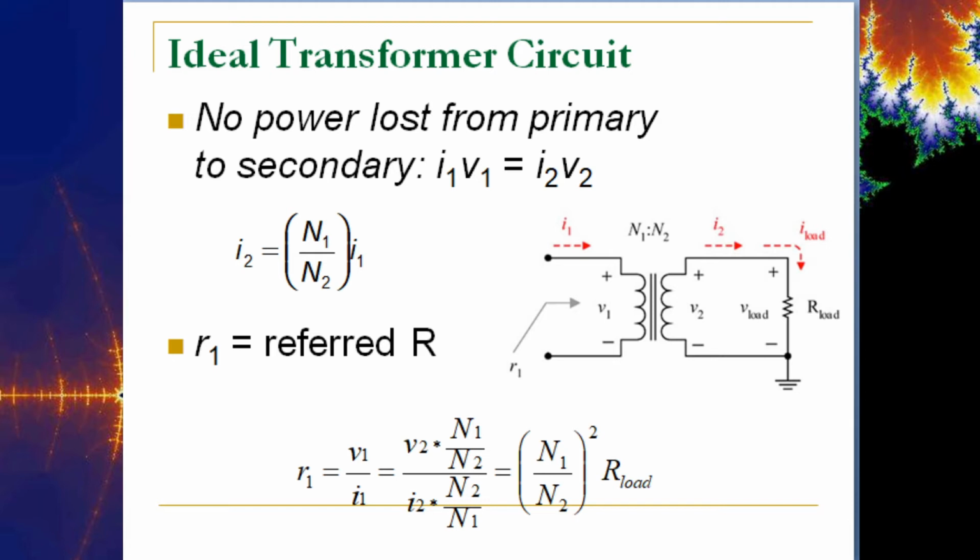the reflected resistance here back on the primary, right? And so we actually use that turns ratio in our calculation to make things simpler. So the reflected resistance back on the primary coil is the turns ratio squared times the value of the resistance of the load. Okay, so this is dependent on what this value is. Obviously if it's a higher resistor, it's going to draw a different amount of current than if it's a lower value resistor. So what is reflected back on the primary that affects the operation of this entire transformer?